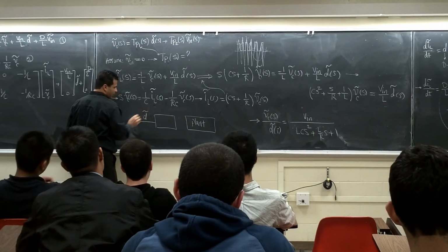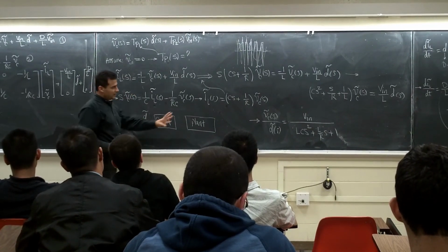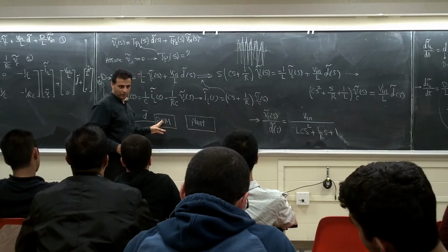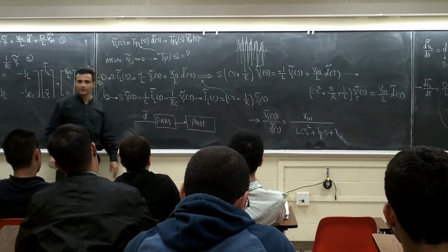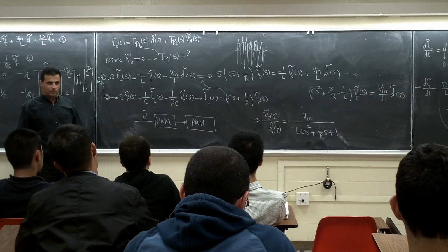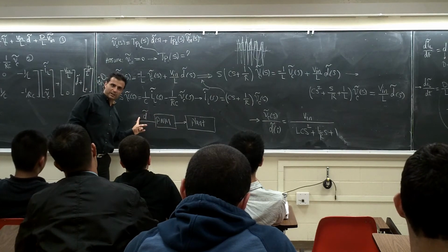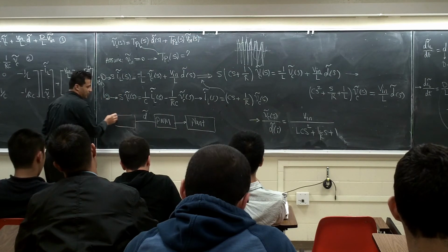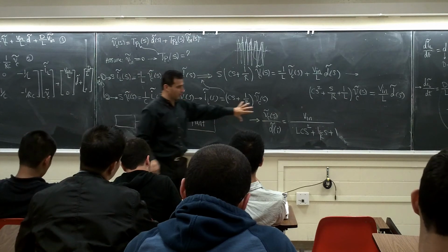You are going to have D coming, it's going to go to this PWM generator, right? This D you have here is going to come to this PWM generator, and this one is going to go to the plant, right? We need to find the transfer function of this one. So D is coming to this PWM generator, and we have the compensator here. So we calculated this one. We calculated this model in this.